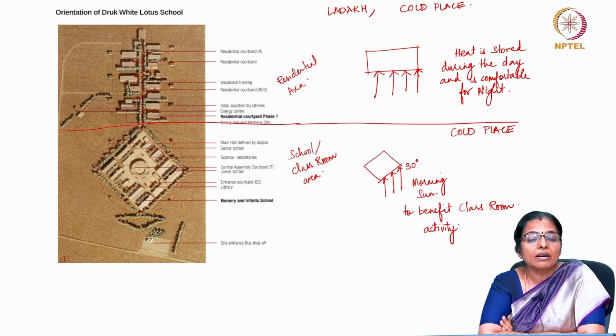The buildings have to be bulky and large. The spaces around buildings must not be porous. They must be compact so that there is mutual shading. Also, openings must be very few, otherwise it will bring in the hot air and also the dust, sand dust, because hot dry regions normally are very dusty.